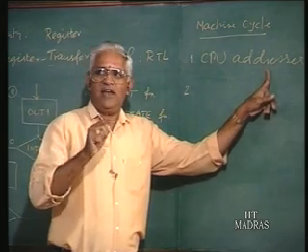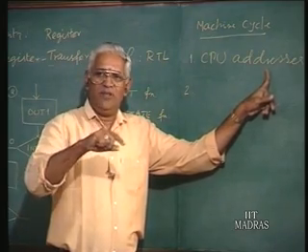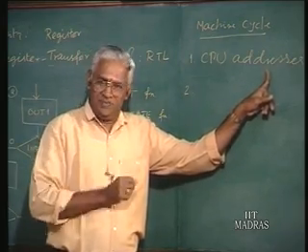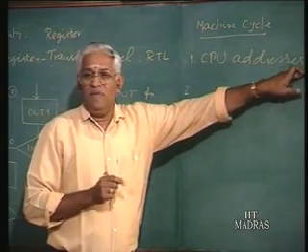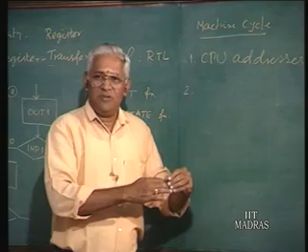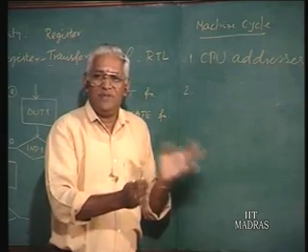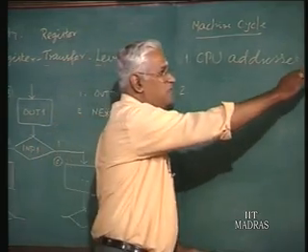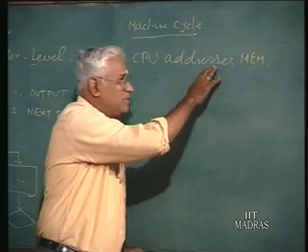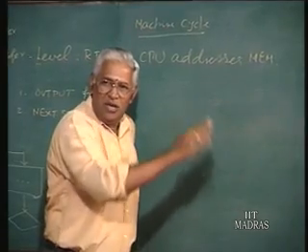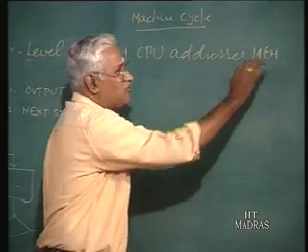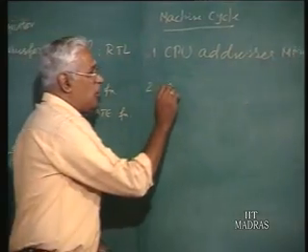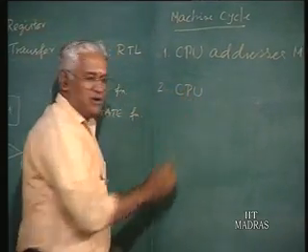The CPU places the address of the instruction on the bus in the case of instruction fetch. Now the memory must know whether it must accept something coming into it or it must respond, because memory is always a slave. The CPU must also indicate that particular thing.